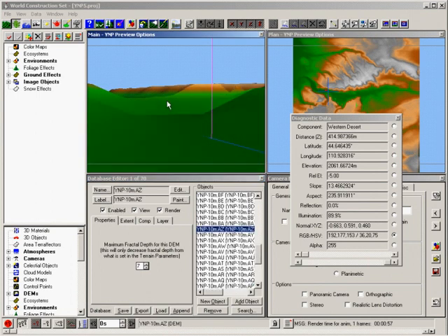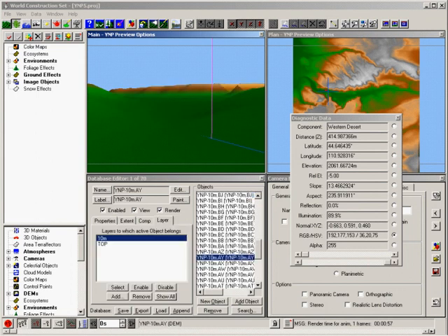The database will identify these as the AP and AZ tiles. Alt-click the DEMs in the background, they're BJ and AY. The two DEMs that would complete the rectangle in the planimetric view are BI and AO.